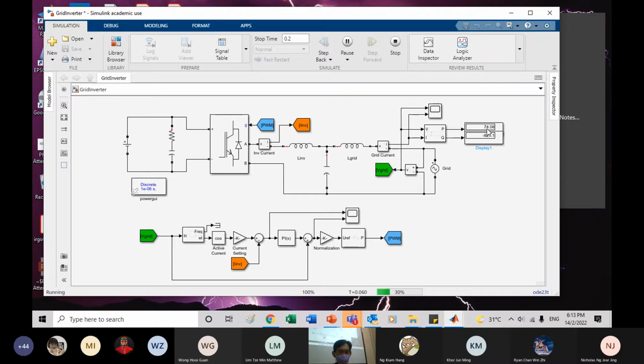And my real power is only 74 watts. Of course, you cannot sell reactive power to TNB. TNB will put a meter there that only reads real power. If you set it wrongly and inject reactive power, TNB won't pay for your 800 watts. It pays only for your 73 watts. Okay. So this is lagging.